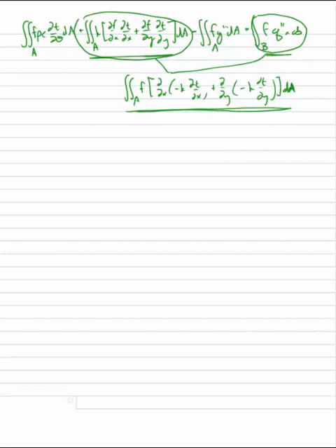So what we need to do now is come up with a form for f, which is our weighting function, and we'll see that there's actually a number of weighting functions that we'll use, and a form for T, which is our approximate temperature distribution that we're going to substitute into this equation. So let's start with T. We know that over our computational domain, temperature is a function of x, y, and θ for our two-dimensional problem.